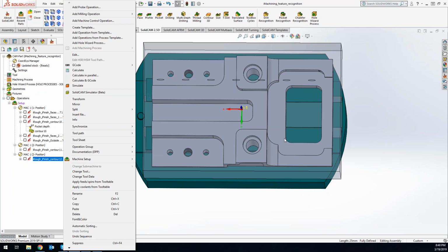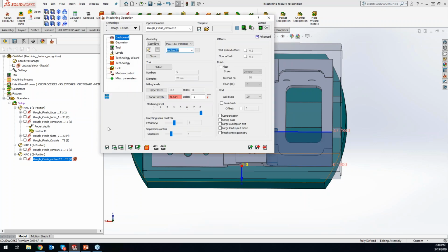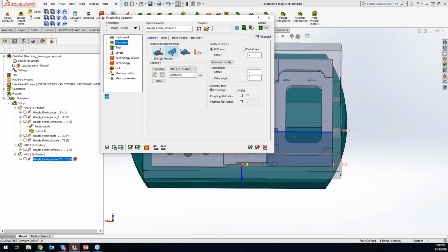Anything I missed there, Greg, for the feature recognition? I think it's pretty good. Just reiterating the points, the new 2D iMachining is now capable of looking at the 3D model and adjusting the tool path if it's going to impede that model. Taking features off of it, the dynamic highlighting of the volume that's going to be removed is a great visual indicator of what that tool path is going to do, as well as eliminate air cuts. So I think you guys are in for a treat with this 2019 release.